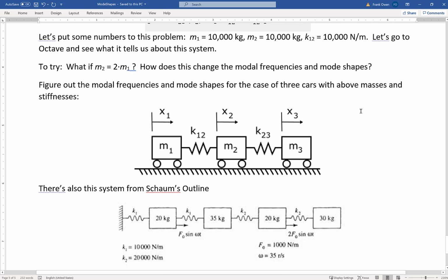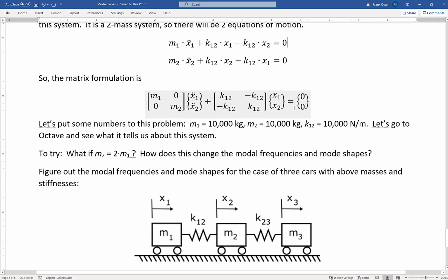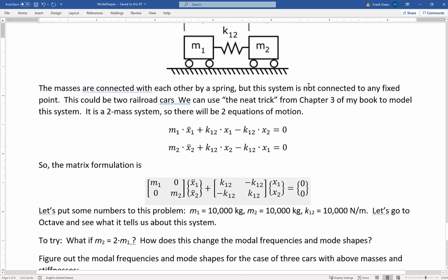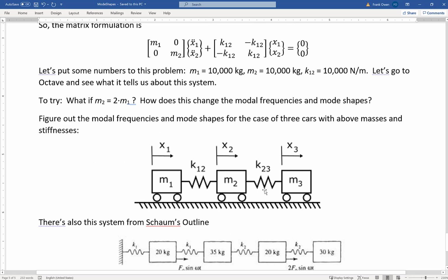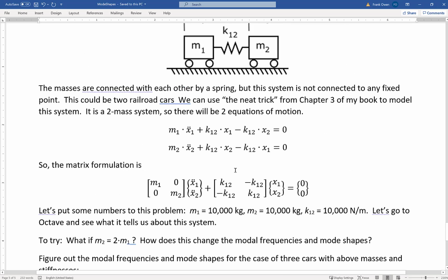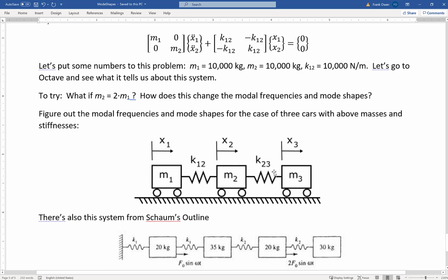It's not so easy to figure out the modes of a 3-cart system. So try that out. I haven't done it. You can use the same values that we used up here. Have all masses the same first, and the stiffness the same. Oh, that's one thing that we didn't do with the first one that we could do, is you could actually have a different stiffness between the two also. So there's all sorts of possibilities for the three mass system, not for the 2 mass system. But if you made these stiffnesses different, then that's going to have an effect.